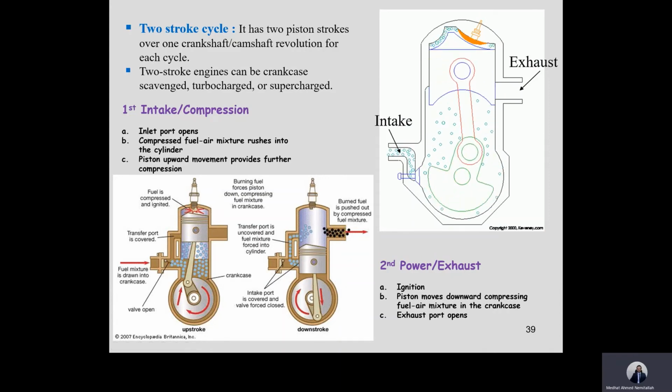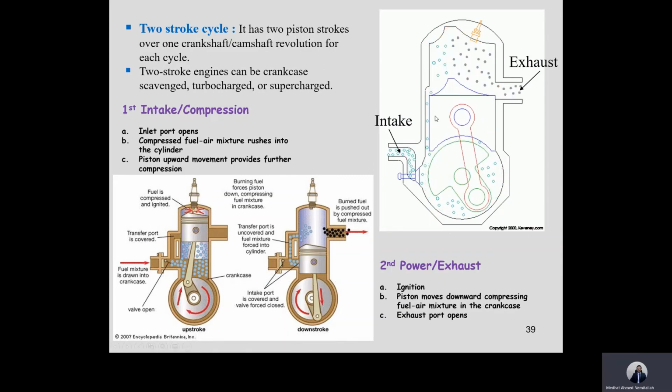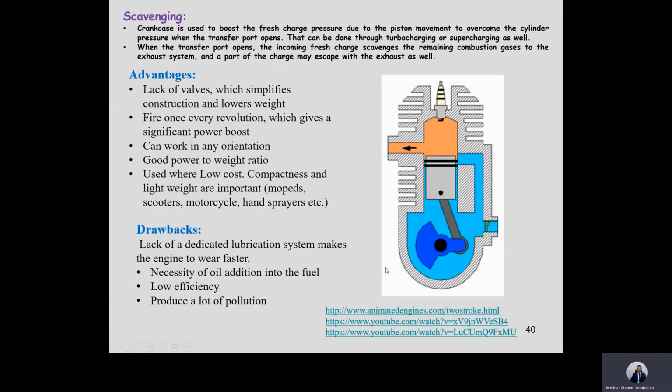And that's why, as I told you, in the case of a motorcycle with a two-stroke engine, you will have some smell. This smell is due to the fuel that is short-circuited without burning, and also due to the oil. Part of the lubrication oil is burned inside the cylinder. So it results in a different smell in the two-stroke engine. And those are the main drawbacks of the two-stroke engine.